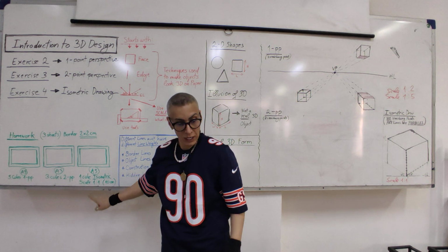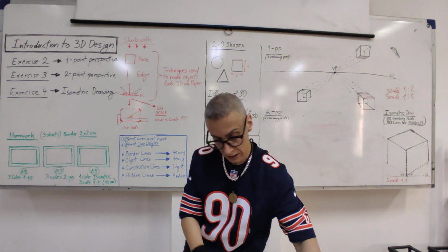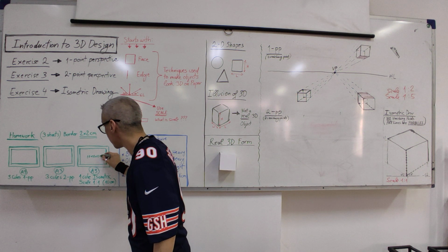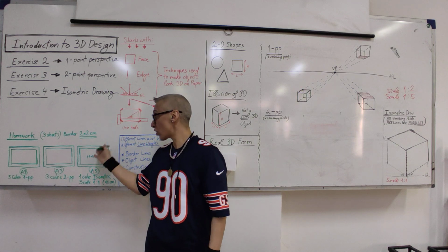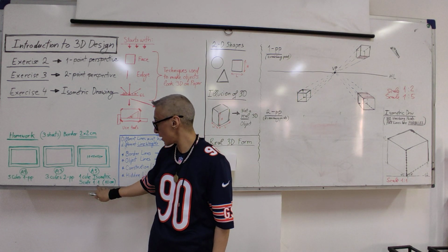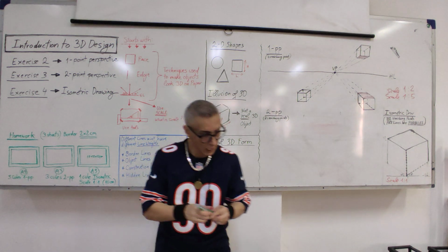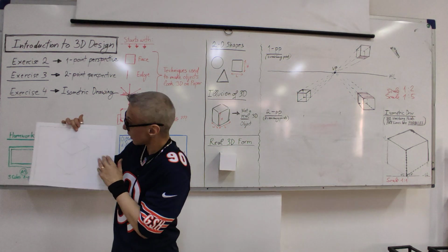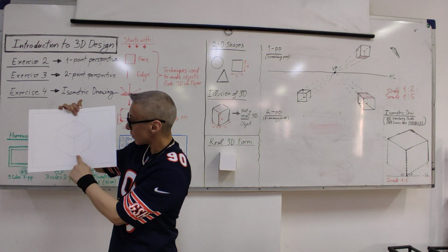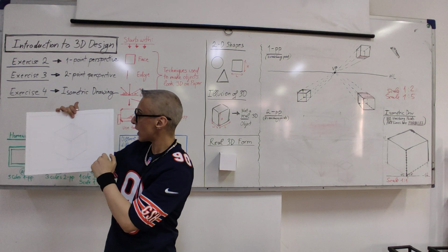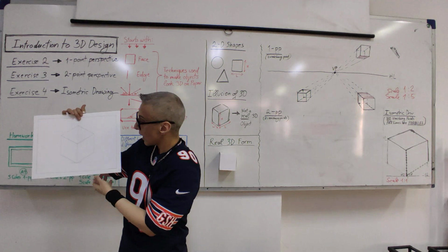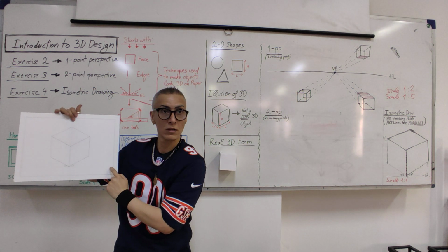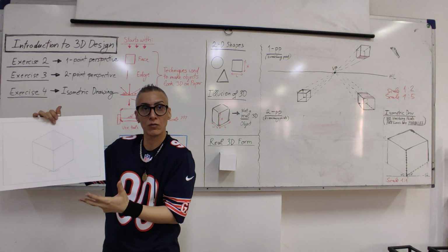Okay? So it should be at 10 by 10 by 10 centimeter cube. And on the drawing, it must be like this because it's scale 1 to 1. Okay? So it will look like this. Something like this, okay? So here, everything must be 10 centimeter, and you must show the degrees, you must show the ground line, everything according to the rules. And also don't forget to write here scale 1 to 1, because you need to get used to these things from now, okay?